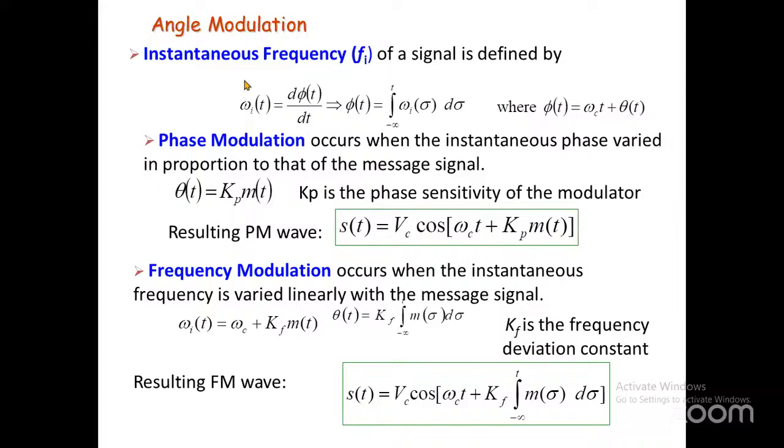So this is the relation of the frequency and phase. If we have a phase modulated wave, by differentiating that wave, you will have a frequency modulated wave. If we have a frequency modulated wave and you integrate, then you have a phase modulated wave.